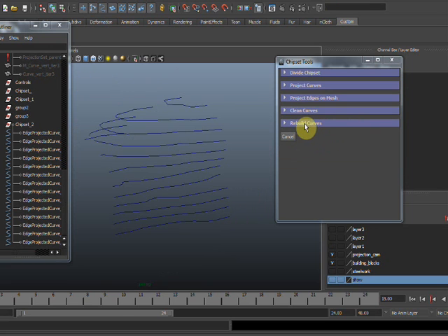The last tool is called rebuild curves, and it rebuilds curves that have more than the maximum number of spans. This is useful for the machine that is going to create steel bars out of these curves. It will probably have a maximum number of bends it can make. Therefore we will need this tool. Here it's set at 40 of maximum spans.